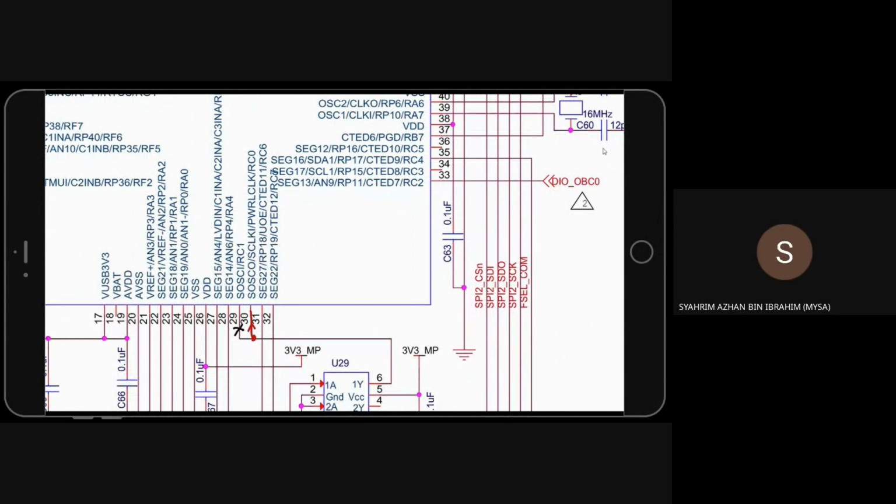I see. So it was a mistake in the first initial design. So I will erase this line. If you can do a small soldering, maybe you can cut this line and connect it to the other pin. Remember, no short circuit between number 29 and 30 when you do it.